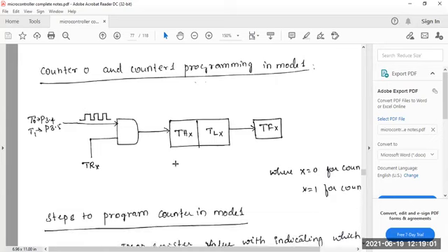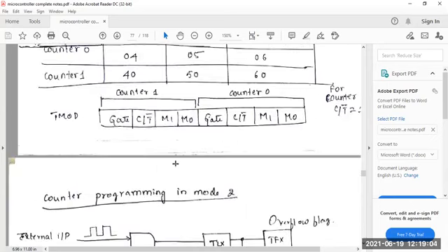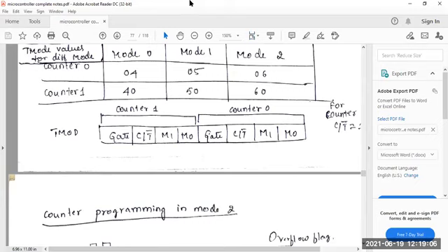As you already know, in the TMOD register, this is the bit which decides whether the register is a counter register or a timer register. If this is equal to 0, that register will be considered a timer register, T0 or T1.